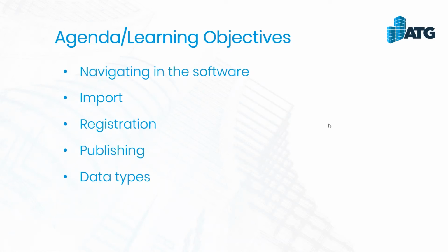I have installed an additional hard drive on my machine, a 4 terabyte hard drive, to be able to do this. So I do all my registering on my D drive, and then when it comes to exporting the LGS or RCP or whatever I'm delivering, I'll push that to the network or to a Dropbox or BIM 360 or however we're doing that.